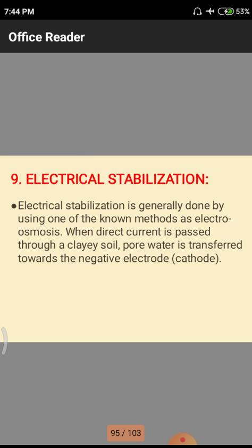After the fly ash we have rice husk ash. This rice husk ash also we obtain in large quantity. Why? Because people mostly utilize rice as a feeding material, so for the purpose of removing the top layer of the rice grains we get this rice husk. And after burning those rice husks for hotels and other utilities, we get this ash, so we have to utilize this rice husk ash also as a stabilizing agent.